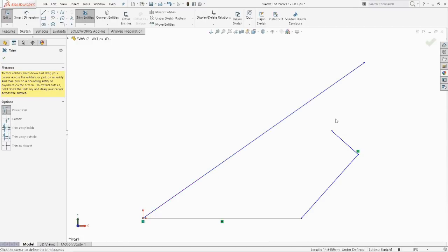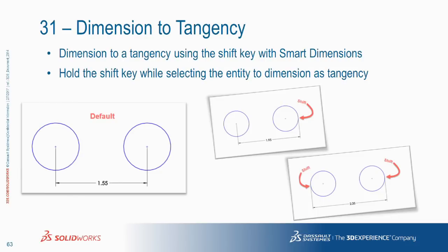But using the power trim tool, you can also use it for power extend. So I clicked on those two lines and extended away. Still in the same power trim tool to just add more to that line, right? So it can be used that way as well, not just to whack geometry away.